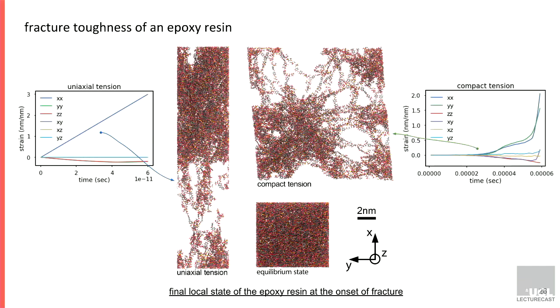If you compare the final states of the two materials, in uniaxial tension you have this type of fracture: a localization of the void growth, and more or less a crack normal to the loading direction. While in compact tension you have a more diffuse void growth all over the sample, and you don't have the same final geometry at all. This impacts significantly the fracture toughness you determine.